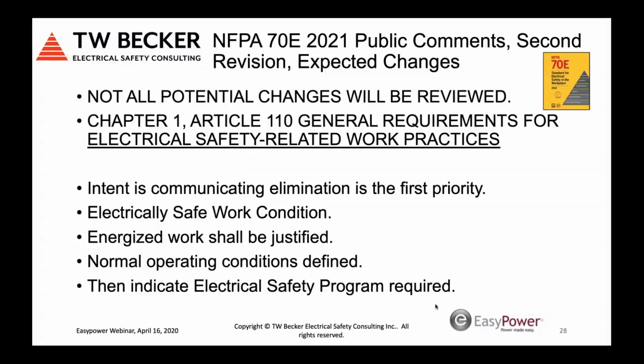The intent is communicating elimination as the first priority. We want to eliminate hazard exposure to arc flash and shock for a worker, and all workers, electrical or non-electrical, if possible. If we cannot establish an electrically safe work condition, then we have to have justification for energized electrical work. And then we also have moved the normal operating condition definition underneath this as well.